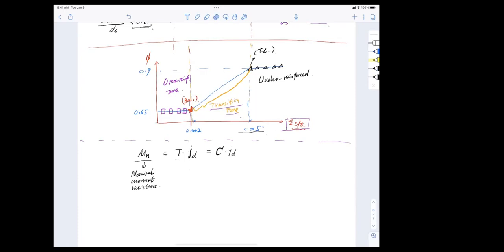So you have tension force, which is As fy, multiplied by jd, and that is ds minus... my next victim here, Callie, Miss Hall, are you there? Hello? Yes. Hey, how are you doing, Callie? I'm good. So the lever arm jd is now equal to ds minus something, right? So minus what? a over 2. Exactly. Thank you so much, Callie. That is the lever arm.